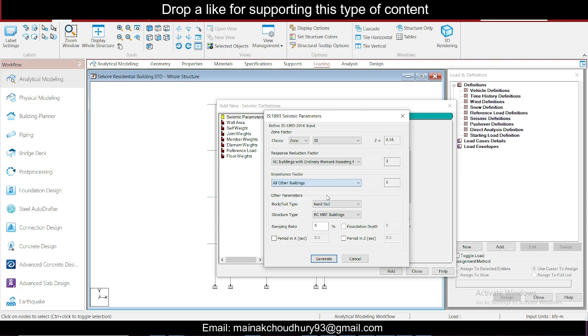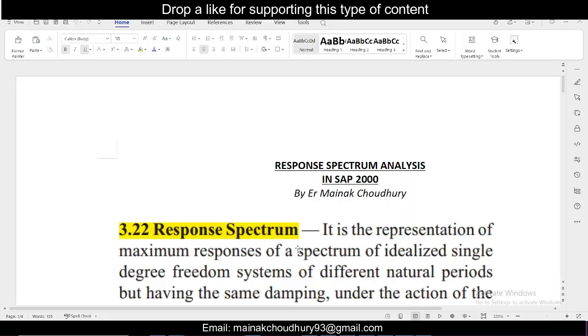So less than 200 occupancy, so I'm going with this soil. Soil is actually very hard, so damping ratio, foundation depth is 2 meter, cement resting frame. Time period, you can change in X and Z direction here for proper analysis, so we'll do that.